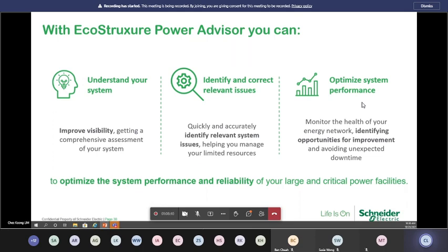When we talk about that, again, I will go back to the principle. Let's say, for example, you have a ward which is being controlled by VAV boxes. All right. So let's say the ward itself, sometimes the temperature goes haywire. Where is the possible root cause of the issue? Could it be the equipment that is failing? Could it be there's insufficient supply coming into the room? Could it be hunting down the line, or could it be something that's happening at the room next door? Right? So this is something that in a traditional BMS system you will not be able to tell. You need to decipher it yourself.